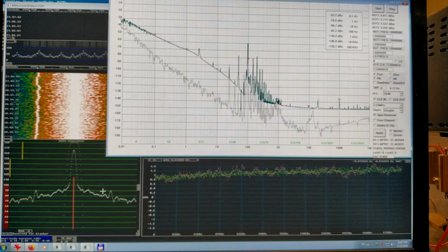That's about 20 Hz. So mixing it in quadrature to get a signal 20 Hz below 10 MHz gives the signal that I'm going to use for phase locking of better oscillators than I have used before with the same method.